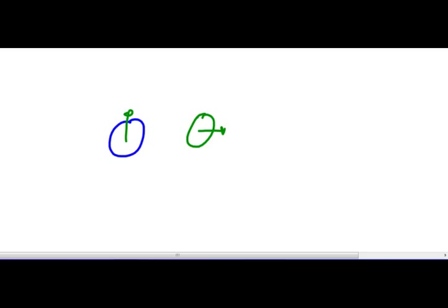So depending on, if I look on the picture on the top of page 652, I see that there's only one set of coils that are closest to the next set of coils. So if I have the number 1 guy energized and I turn on number 4 next, it's going to rotate counterclockwise.